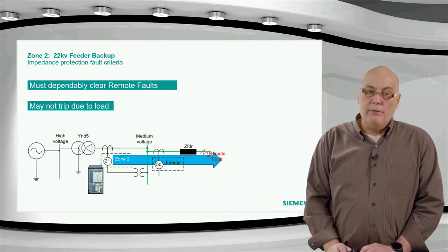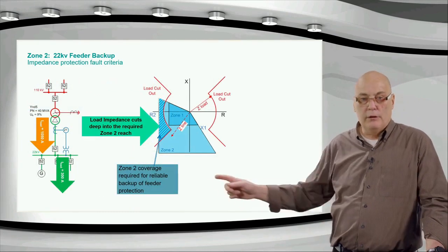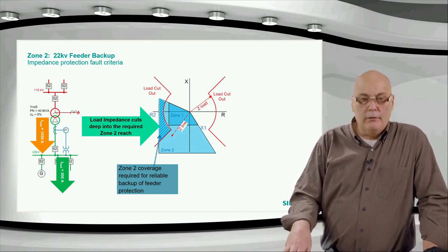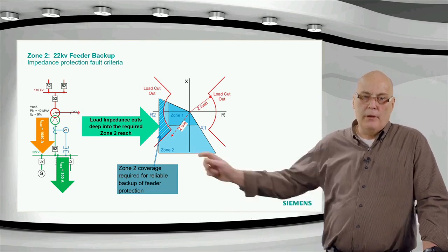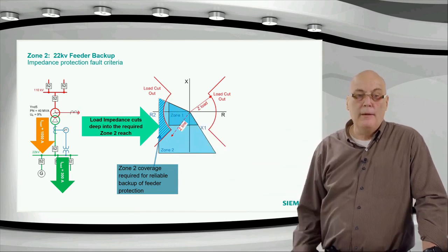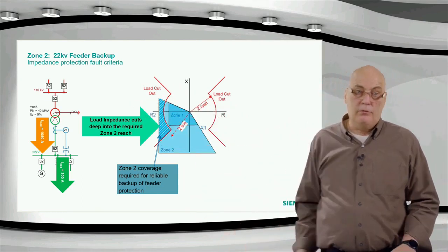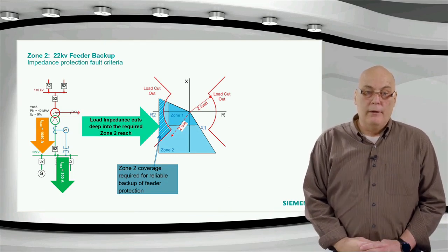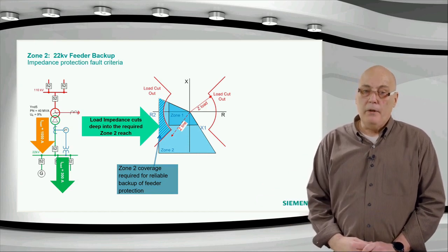All right, and that is difficult because we have a coordination of load and fault in-feeds. You can see here at the bottom, the feeder might have a 300 amp load current, and the according setting may be set to 400 amps to coordinate with the load, tripping at 400 amps down there, and the fault, the load current on the transformer, all the feeders in parallel. If you have a 40 MVA, I can now see I've gone up to 40 MVA with the transformer. That's typically what's happening. You get 1,000 amps full load current, all the feeders in parallel, but each individual feeder only 300 amps. And you have to get a pickup.